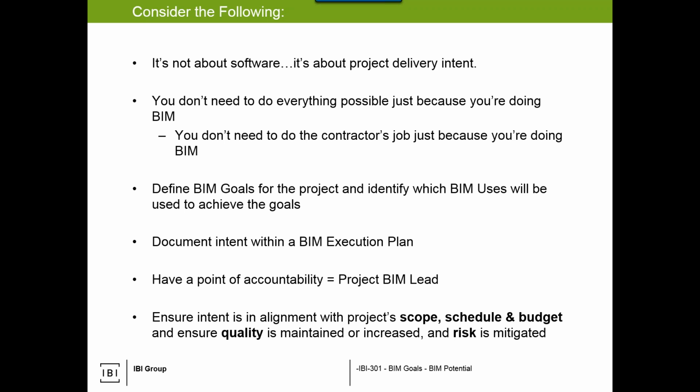Document the intent in a BIM execution plan. We have templates, we have procedures, if we have a quality management approach where we want to say everything should be planned and have your point of accountability, so have your lead. Now, for the gamut of our projects, you might be saying, well, that sounds like a lot of effort, and maybe it is the first couple of times, but I would argue that if we sat in a room and we stated our intent verbally, and then we emailed the team, in essence, that's a plan, right?